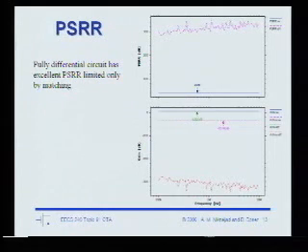So this is a good example that shows you a fully differential circuit rejects the power supply, but the simple differential circuit did not. Also, why is it just 300 dB? Should it be larger? That's just numerical noise, right? It's finite precision, and so really it should be infinite for a perfectly balanced circuit.